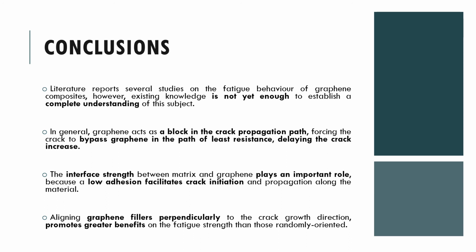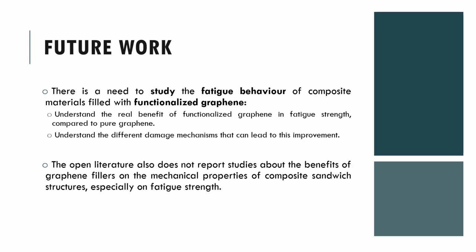We can also conclude that the interface strength between matrix and graphene plays an important role because low adhesion facilitates crack initiation and propagation along the material. We can also conclude that aligning graphene fillers perpendicularly to the crack growth direction promotes greater benefits on the fatigue strength than those randomly oriented.